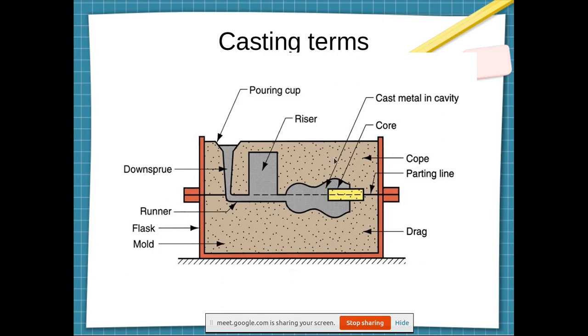Now, once I'm done with pouring the sand, I will remove these boxes. These boxes, I will take them out. I will unclamp them and I will remain with this sand. Then I will take the molten metal and pour it. This hole is made by something known as a sprue pin. I don't know if you saw him start. He put a pin in this before pouring the sand. So he puts the pin, then he puts the sand. Once he's done ramming the sand, he removes your pin, so the hole is formed. That is the hole that you will pour the metal into.